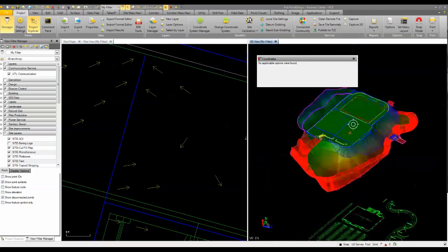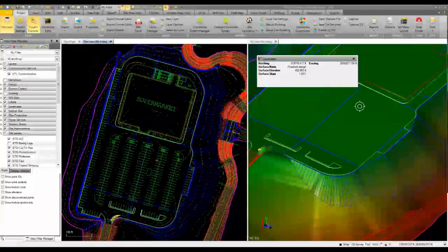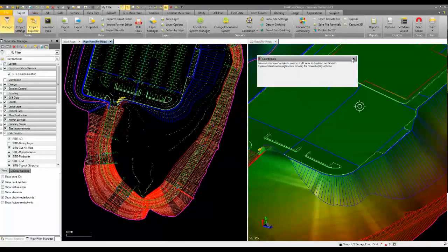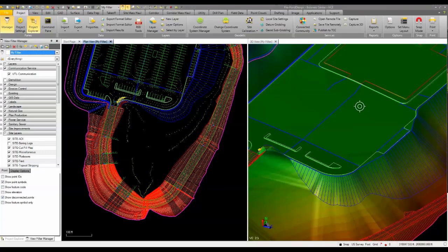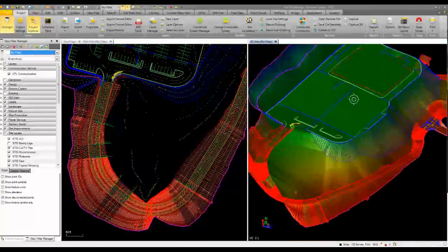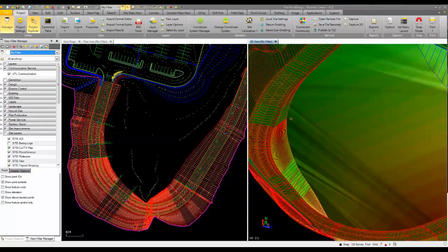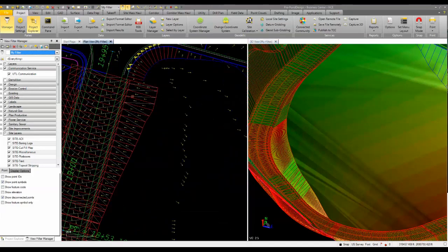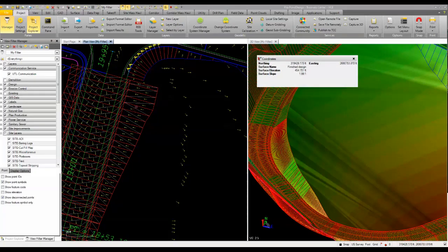All right, so we're just going to move this guy over here, and we'll come back down into here, and let's close that for now. So down in this area, right now we've just got this daylighted out, and we know that we're going to have to change it. So if we look a little bit closer, all the runoff, we know we're cutting in here. So we know our elevation. Actually, let's open up our coordinate scroll. We can see that our finished design elevation up here is 454, and we know that our top of pond is going to be lower than that at 444.